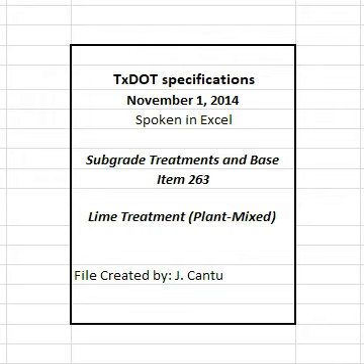3.3 Spreader equipment. Provide equipment that will spread the lime-treated mixture in a uniform layer in one pass when shown on the plans. Equip spreaders with electronic grade controls when shown on the plans. 4. Construction. Construct each layer uniformly, free of loose or segregated areas, and with the required density and moisture content. Provide a smooth surface that conforms to the typical sections, lines, and grades shown on the plans or as directed.